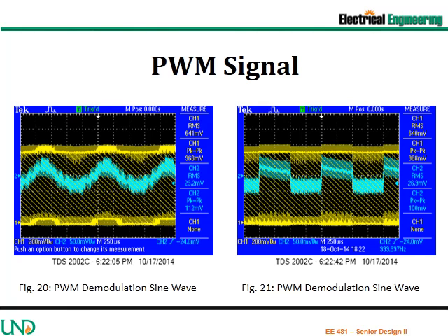By sending the pulse width modulated signal to the same envelope detector as the AM signal, we are able to recover the original audio. The pulse train frequency is set to 5 MHz with a duty cycle of 50%. The deviation is set to 25%, which results in the cleanest sounding signal. As you can see, there is much distortion for both signals.